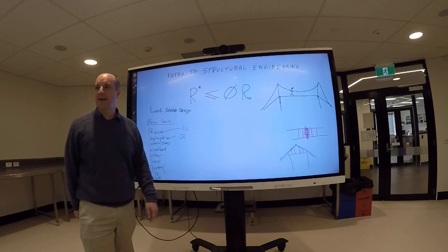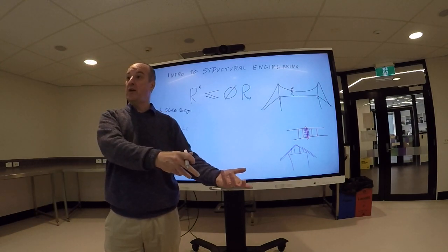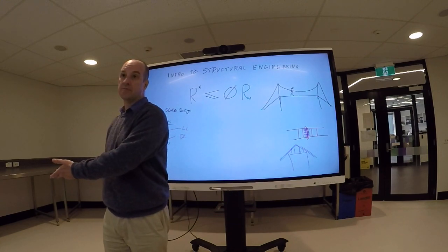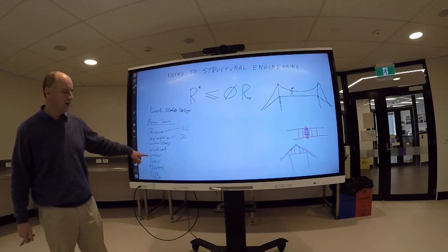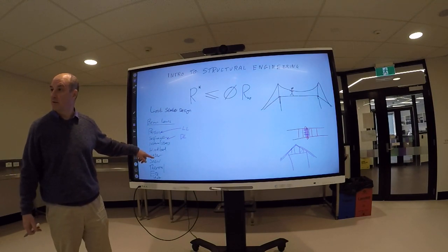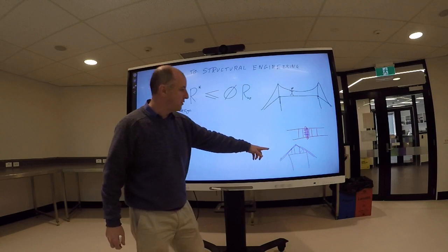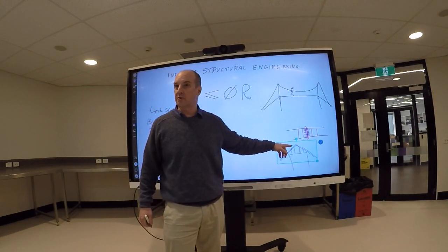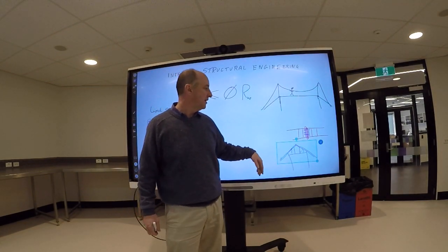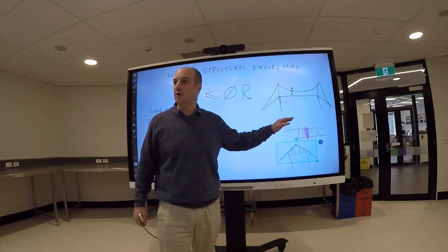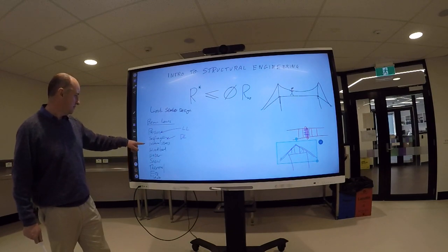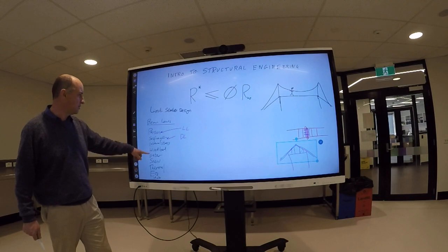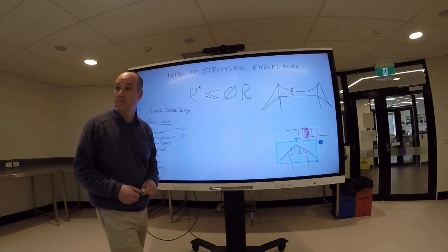Live load is anything that can be on there and might not be on there. Okay? So strictly speaking, wind is a live load, but we treat that separately. Water is definitely a live load when rain falls on it. When rain falls on this roof, you're going to get at least a few millimeters of water on the roof before it can drain off. When you get snow, snow can collect on the roof. We'll leave internal stresses out for a minute, but most of those others are live loads. Okay?